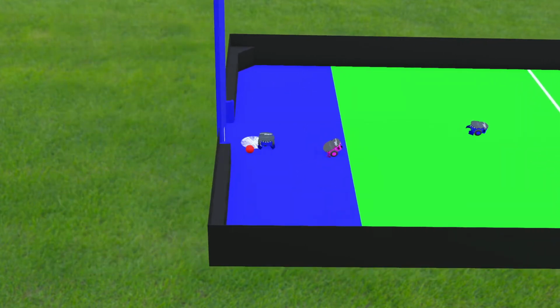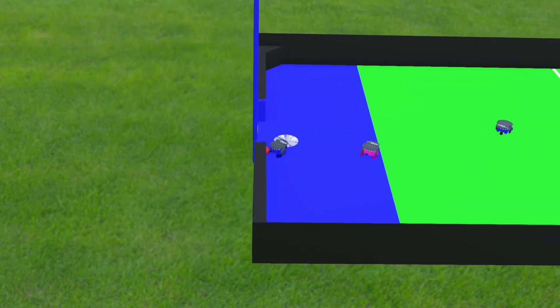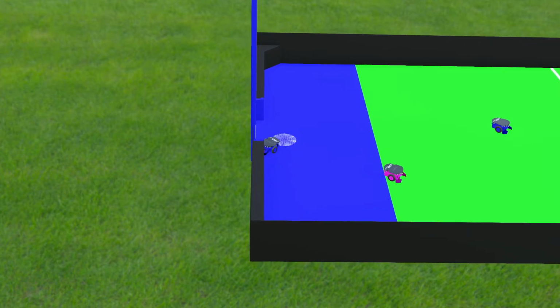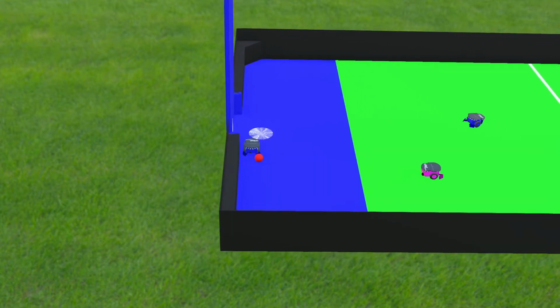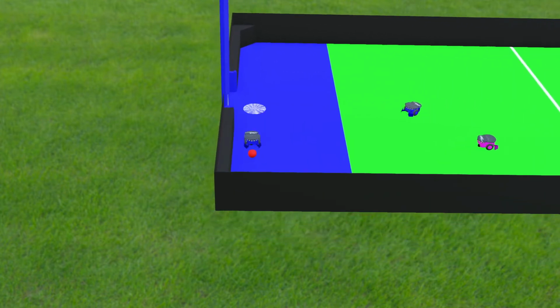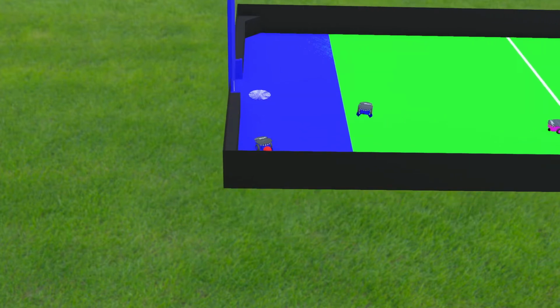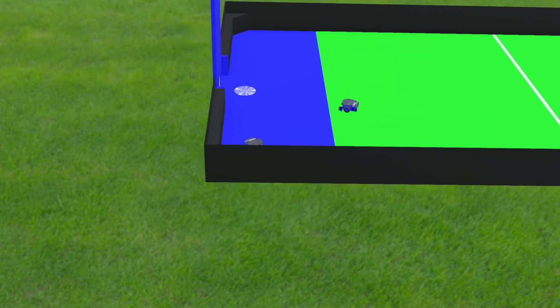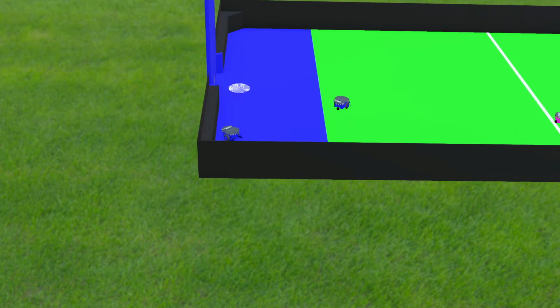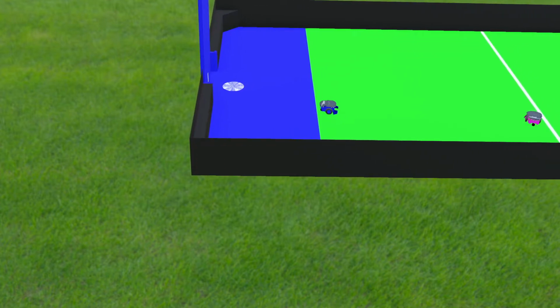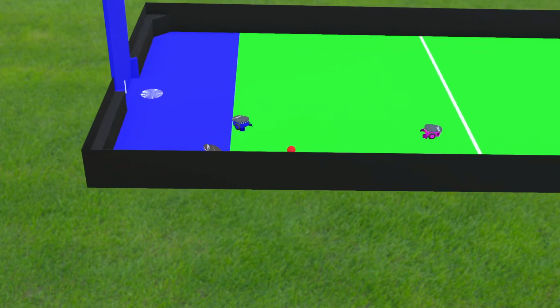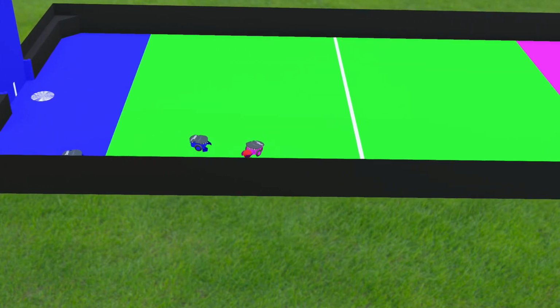And once they're open, the next state will be triggered while the robot is put into drive forward, and that next state will monitor the acceleration of the robot. So it looks for a very aggressive acceleration. Once that's happened, then it applies the brakes and then looks for another aggressive deceleration.